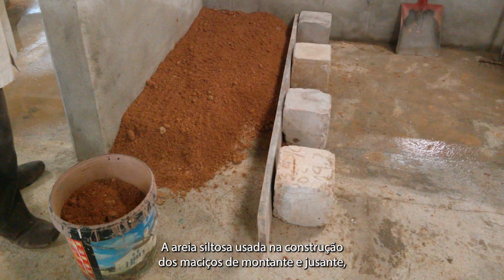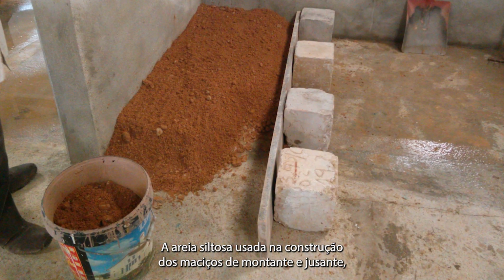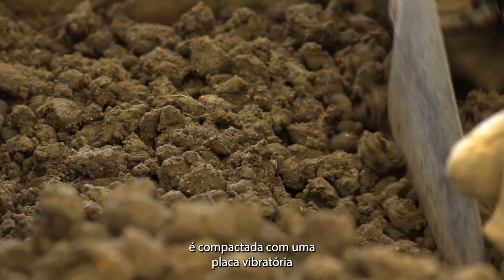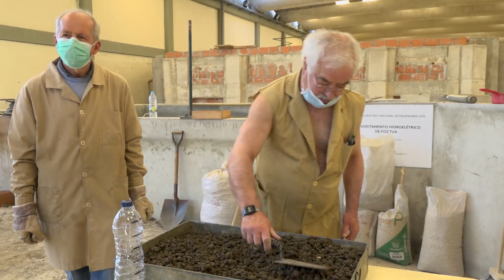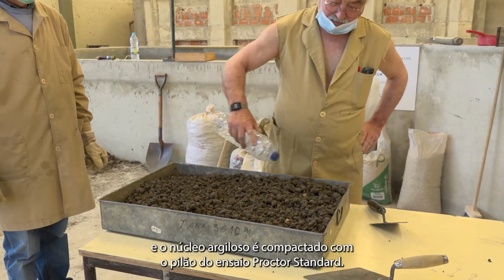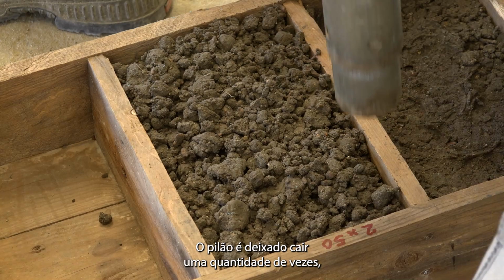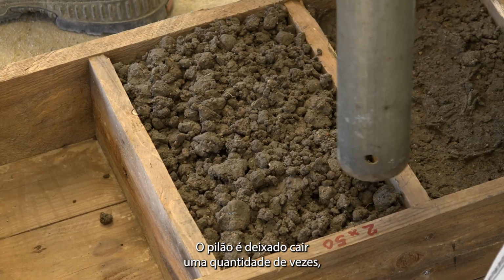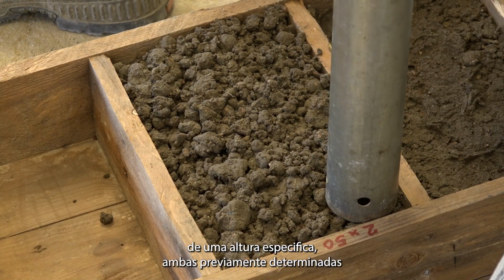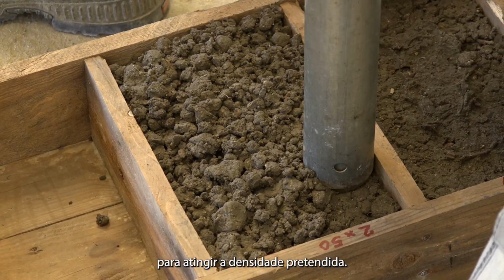The silty sand used in the upstream and downstream slopes of the dam is compacted with a vibratory plate, and the clay core is compacted with the use of the hammer from standard Proctor test. The hammer is dropped a number of times from a specific height, both previously determined, to achieve the desired density.